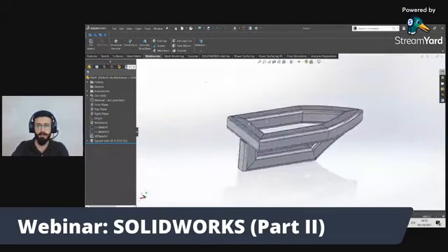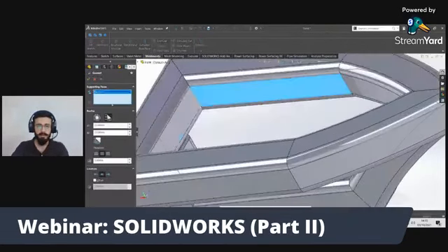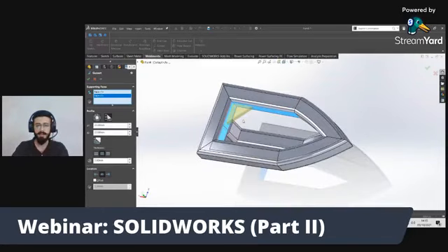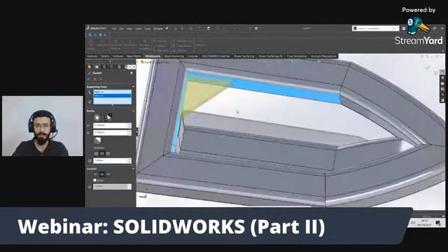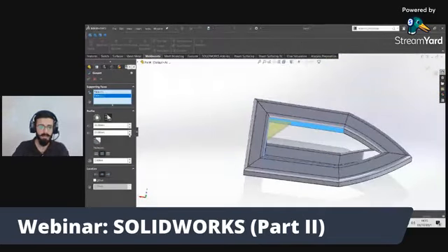There is something more we can add in the weldments. If you want to support these two perpendicular pipes, we will just add a gusset here. See, as in preview, let me zoom in. This is the support you are adding. We can reduce the size of it. That's good.